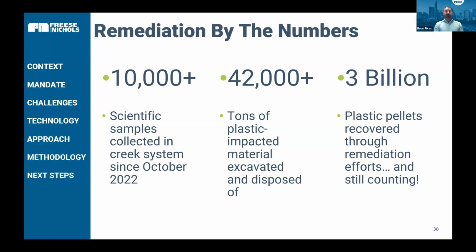And while we're really excited to have that level of removal, one thing that I'm sure is very obvious to everyone as you're looking at this is what's happening to that soil. Why do we have to send it to a landfill? And this goes back to that lacking technology component that we're all wrapping our heads around right now, which is there's not an easy way when working in these soft clay systems to really mechanically separate soils and plastics without it taking 10 times as long and costing 10 times as much money.